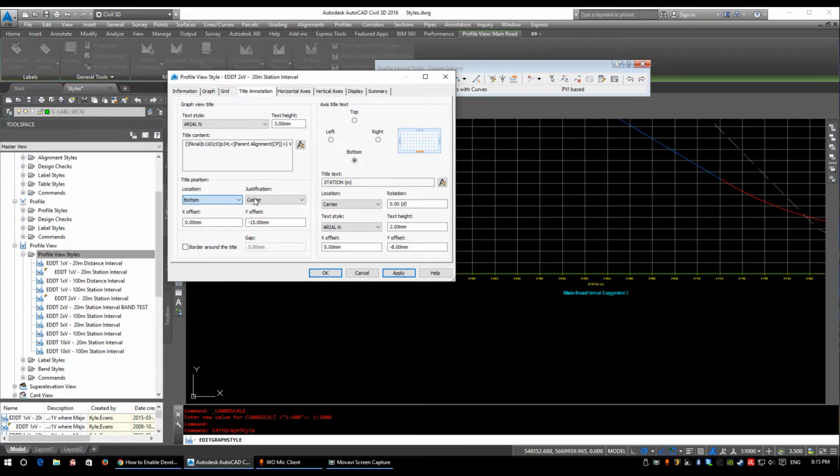This is where we want it located: bottom, center, any offset. So if we change that to -20, it's going to drop it down a little bit further. If you notice over here, we have bottom, right, top, left labels. So as we select these, the information down here changes. So along the bottom, I have station now. So if you see right here, there's a little station. This label controls down here. These two control the elevation and different offsets. And I don't have a label at the top showing. There is one that says station, but I have it turned off.